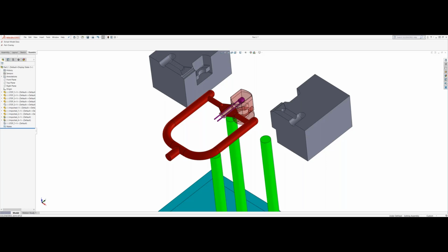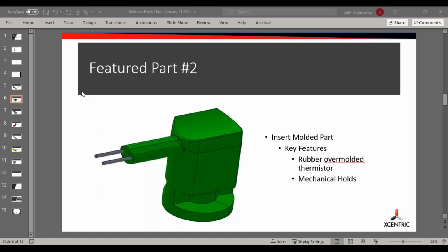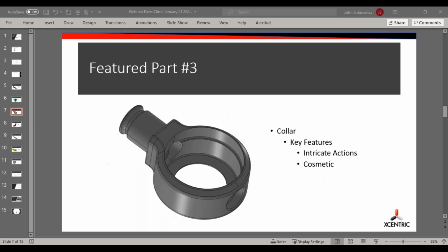The second question is, is the mold sometimes heated to provide better flow? Yes, molds will have to be heated or cooled to be at a certain temperature for that material to cure and run properly. The manufacturer provides a range, and our head of molding runs our tryouts, and he will play within that range. Sometimes maybe go a little outside that to get a better fill and flow. It really just comes down to the particular part and wall thickness, and there are a lot of variables that go into that.